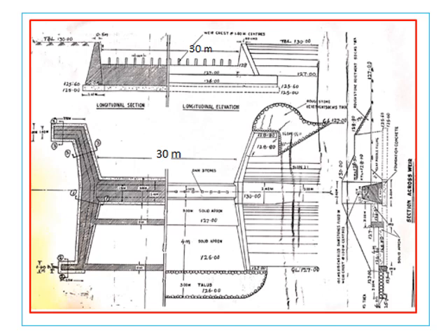So now you can fix the top of the bund onto the sections there and decide the earthwork calculations. That is part of the survey work, and you can calculate the volume of earthwork that has to be done for the bund. Also, you can calculate the earthwork for the canals. So you can finish off this tank project.